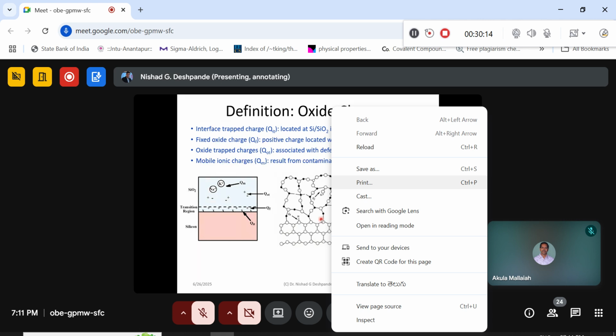I was expecting that when I'm growing the silicon dioxide on the silicon surface, the crystallinity should follow the same structure. So I should get the same hexagon kind of structure growing over this particular layer. So what happens, let's say during the growing process, the diffusion and the reaction processes at the interface, if there is some break or the bondings are not properly formed here? The crystallinity will break here.